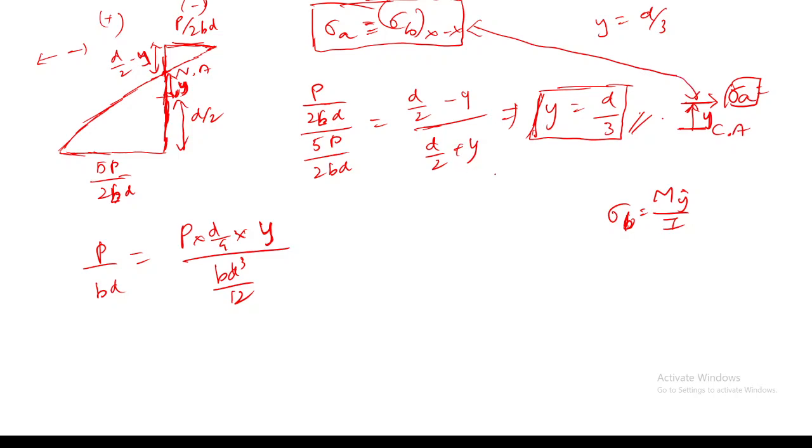Are you getting what I am saying? See, at this point, the negative bending stress value is equal in magnitude to the positive axial stress value. So here we are not worrying about the sign. We know from this variation that the neutral axis is located between the centroidal axis and the top fiber. On drawing the variation, we come to know this.